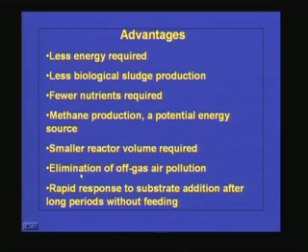So, sludge handling is not a problem in an anaerobic system, and another one is that since the sludge generation is very less, the nutrient requirement is also less, because we have seen the empirical molecular formula of biomass. Each unit requires a particular amount of nitrogen, phosphorus and other micronutrients, but if the total amount of sludge generated is less, then definitely the micronutrients and macronutrients required in the system will be reduced considerably.